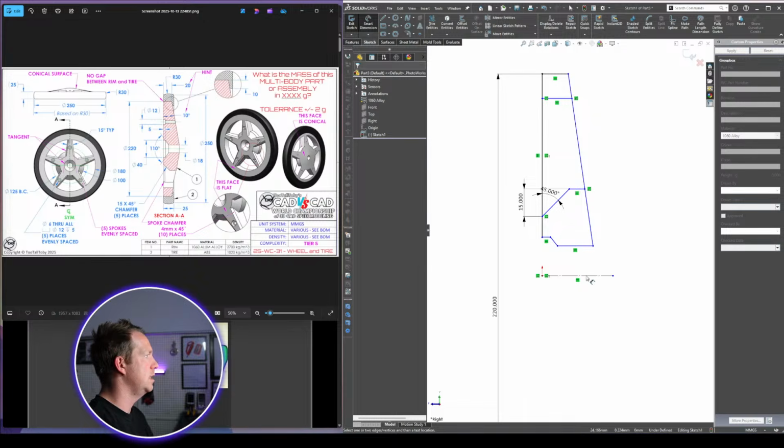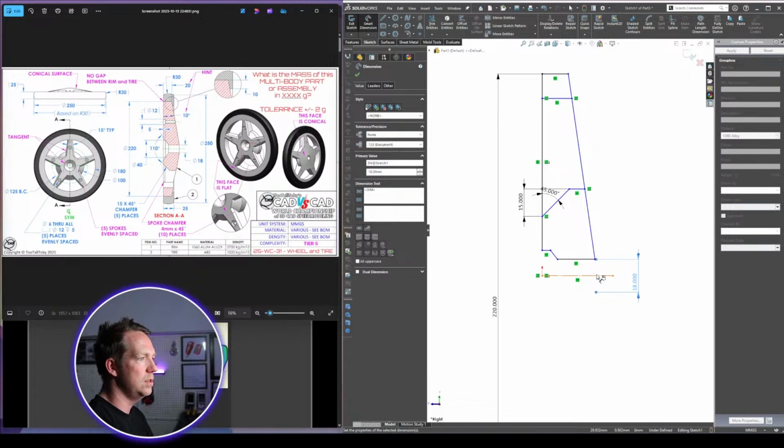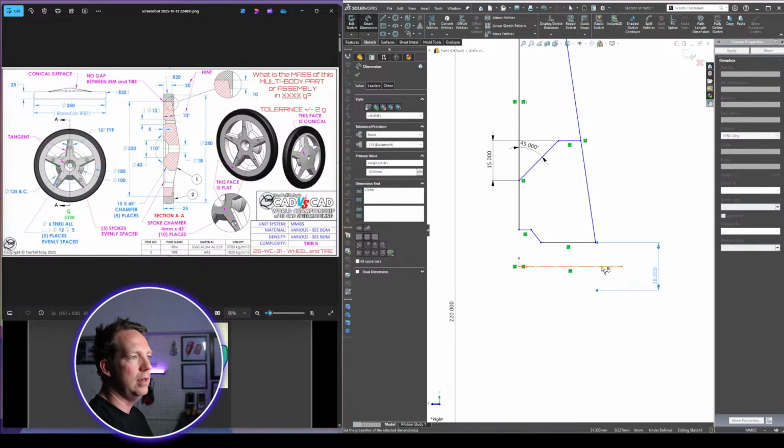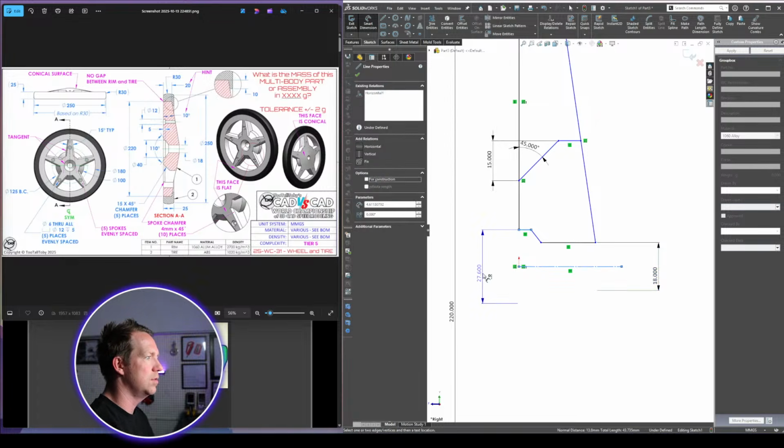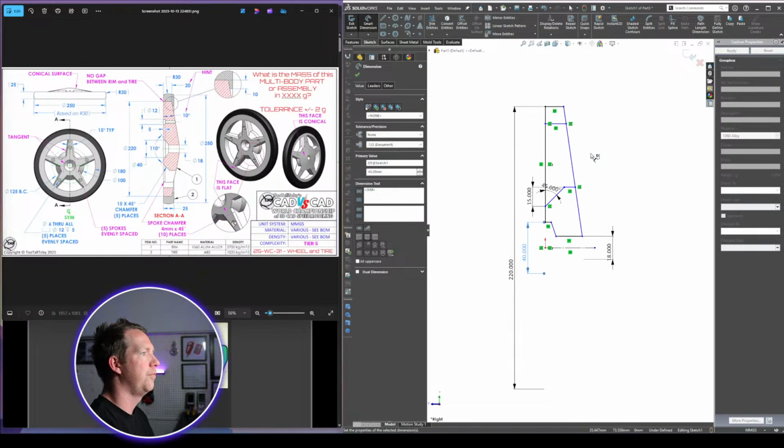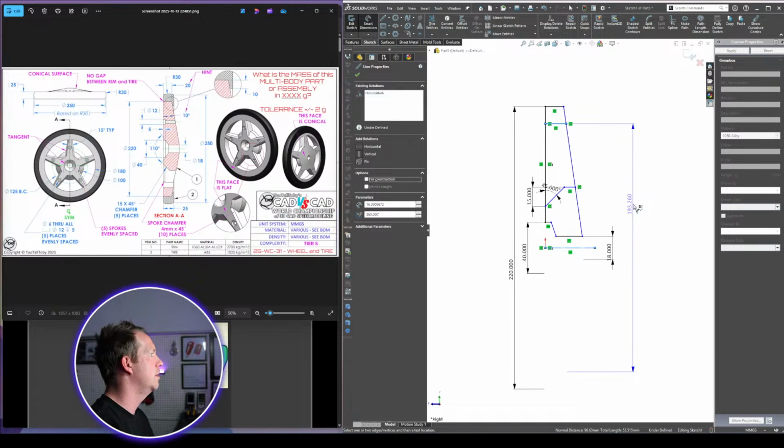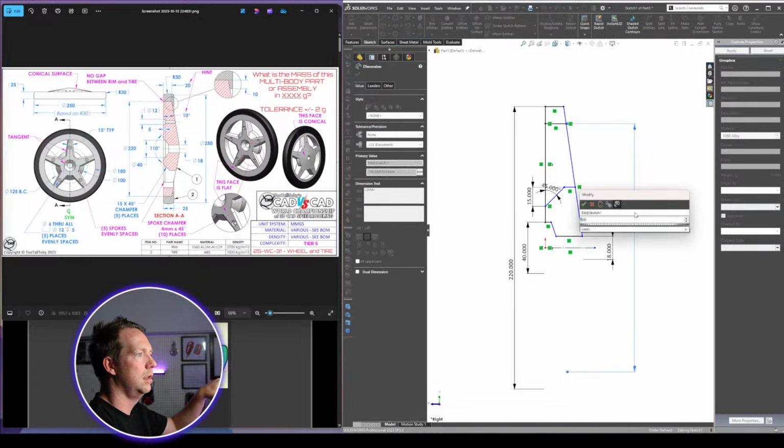So let's add some others in. We get 18 across the middle. Now, trick: once you use one center line for your dimensions, you see that D and the construction line on my cursor. That means I can do others in a similar fashion, which makes sense to do something like this one, 40. Okay, this edge here. Now I have to try and find that dimension. For this dimension, I have to look at the side view or the front view, which is the 180, like that.